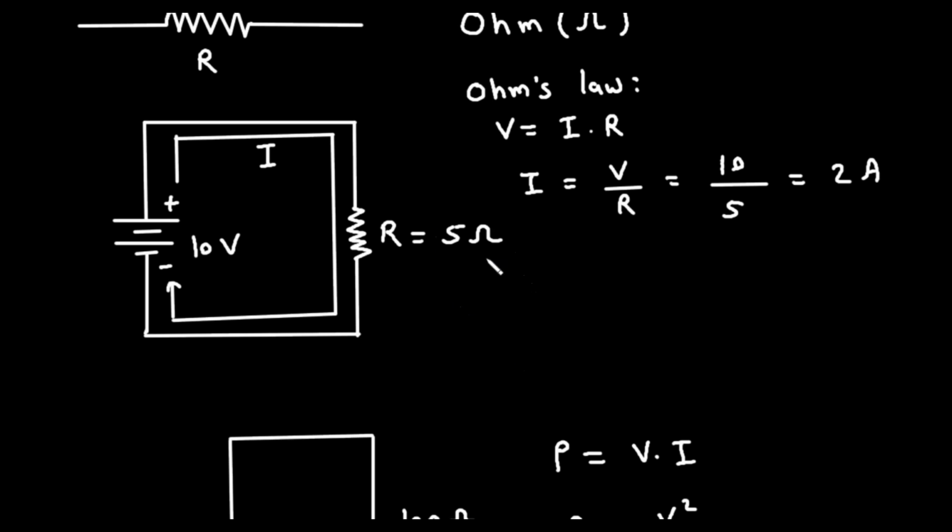Suppose if we want to divide the voltages between components, then we use resistors. Then to pull up or pull down digital inputs, that time also we use resistors. Then to set time delays in combination with capacitors, that time also we use resistors.